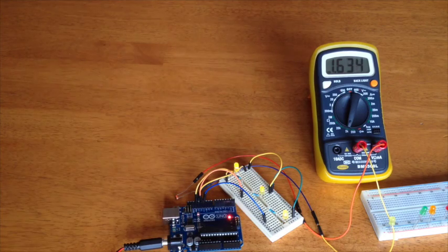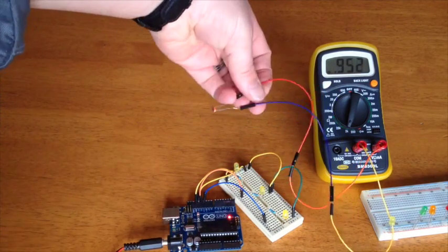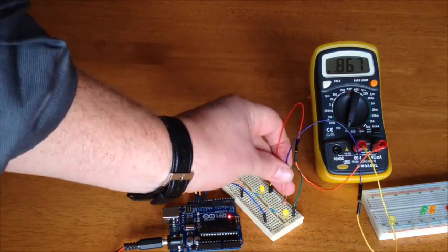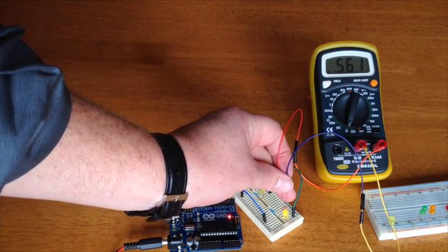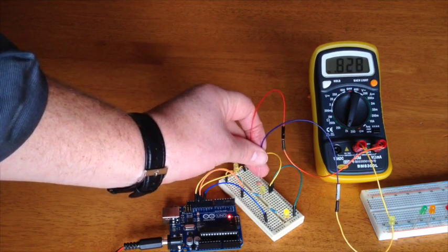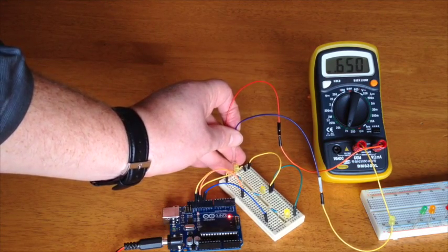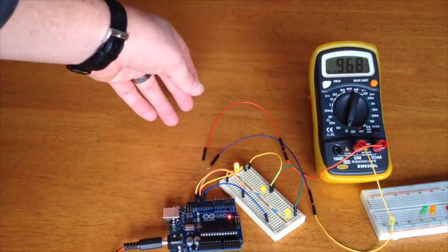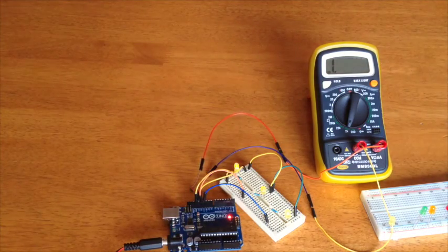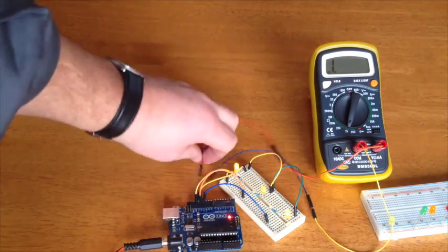That's like the light from a power supply, for example, which has a frequency of 50 Hertz. We don't see it turning on and off because our eye has what's called persistence of vision. Okay, so we could measure the resistance at a high frequency, which is 0.5, at a lower frequency, 0.7 approximately, and a very low frequency, we're down to about 0.6. So there's another option that you could do. So there is plenty of things for you to explore with this LDR.